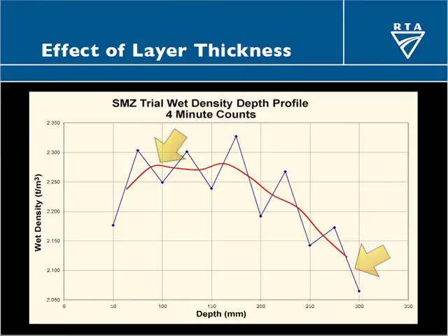The red line is a little bit of elementary curve smoothing, and you can see from that we've obtained very good densities, probably down to about 200mm or just below, just above, and below that the achieved density starts to fall off fairly rapidly. And to give you an idea of where we are, the highest part of that curve between about 75 and 175mm is equivalent to about 107% of standard compaction. Drops to about 95% at the right hand end and is clearly heading south fairly rapidly.